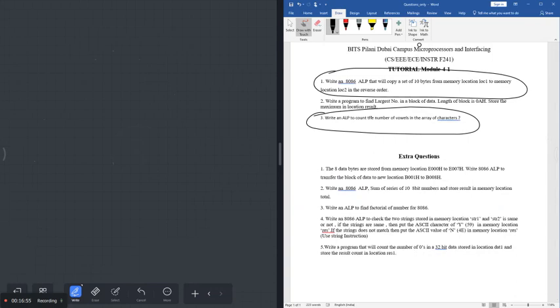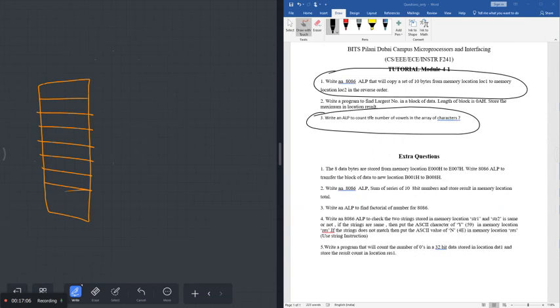Right. So logic is very simple. You have these 10 numbers in an array: 1, 2, 3, 4, 5, 6, 7, 8, 9, 10. You point to it by some pointer SI. Suppose this is called array 1. So what you do? Load effective address in SI, comma array 1. Its offset address is loaded into the register SI. It is pointed by the SI register now.